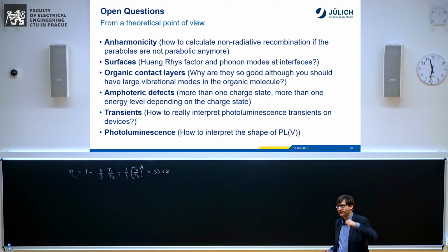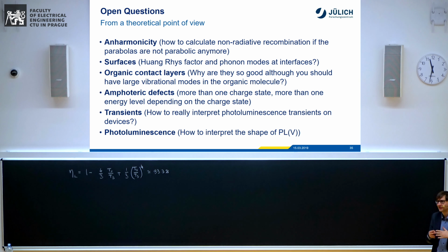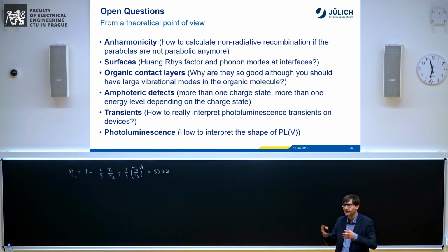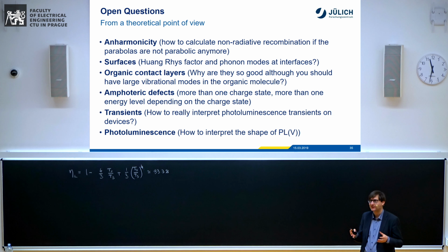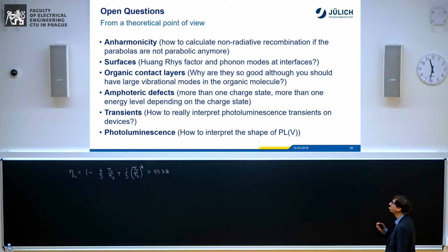With a sufficiently high band gap, at some point multiphonon transitions will become infinitely unlikely. But still, it took a Nobel Prize and probably two decades of work to get gallium nitride good enough to make a blue laser. And there are people trying to think about this, but it is also not entirely clear to me how to explain non-radiative recombination in high bandgap semiconductors.